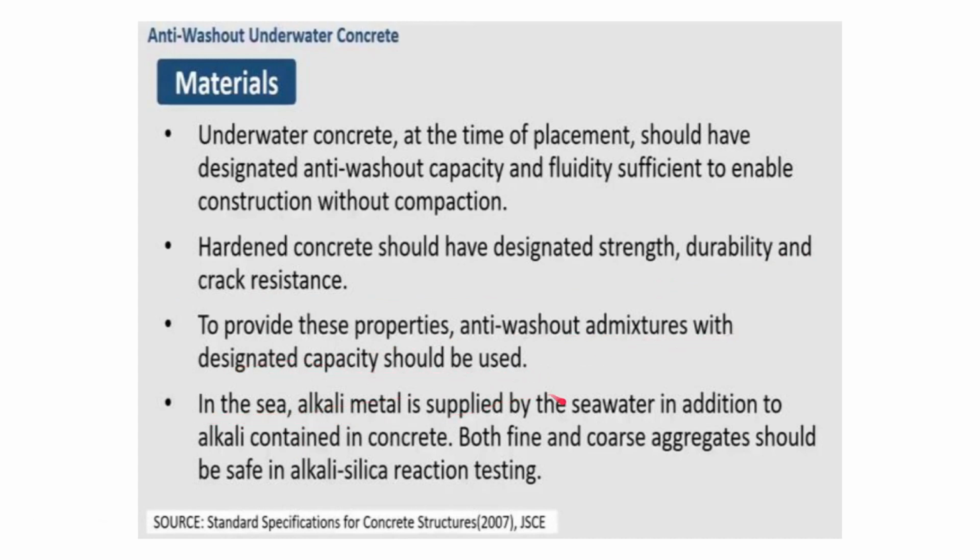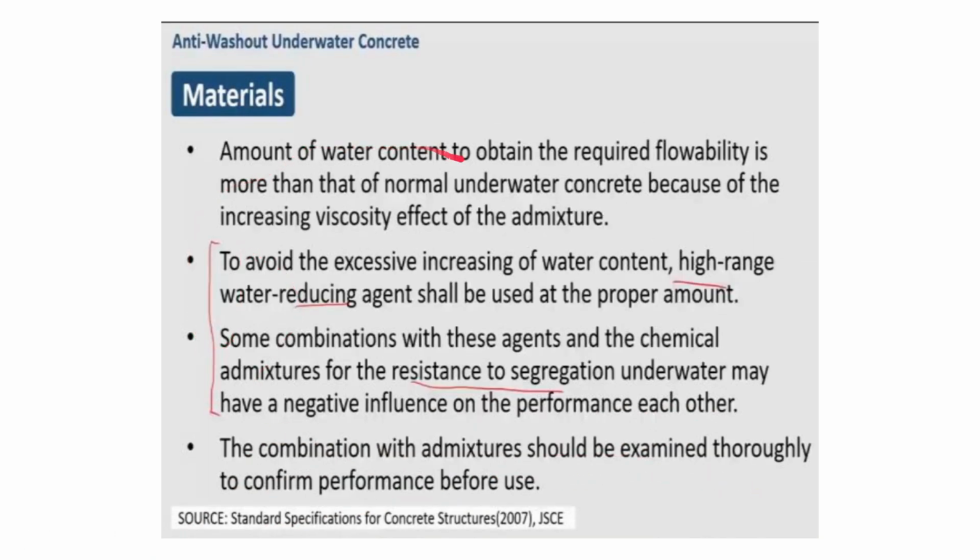In the sea, alkali metal is supplied by the sea water in addition to alkali contained in concrete. Both fines and coarse aggregates should be safe in alkali silica reaction testing. Okay, the amount of water content to obtain the required flowability is more than that of normal underwater concrete because of the increasing viscosity effect of the admixture. So because we have used a lot of the viscosity agent, the amount of water required to achieve the same flowability as compared to normal will be more. Okay, to avoid the excessive increasing of water content, high range water reducing agent shall be used at the proper amount.